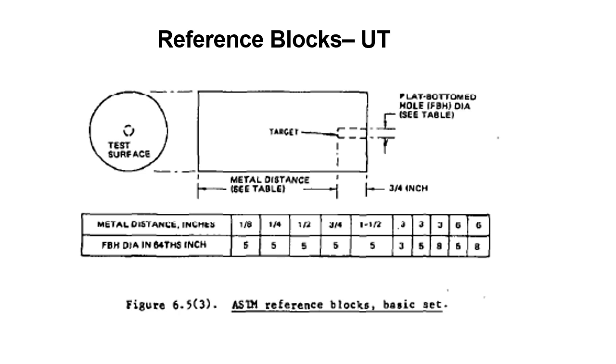So you can make a flat bottom hole, and then there's different sizes where you'd make them of different sizes, and then you'd use the ultrasound to go down, bounce sound waves down there, and look for that hole of that size, and then it would tell you if your machine was calibrated to find a hole of that size at that depth. So you just set it off of this table. So if you want a 1/4 inch at a certain depth, you make a block like that, or you buy them.